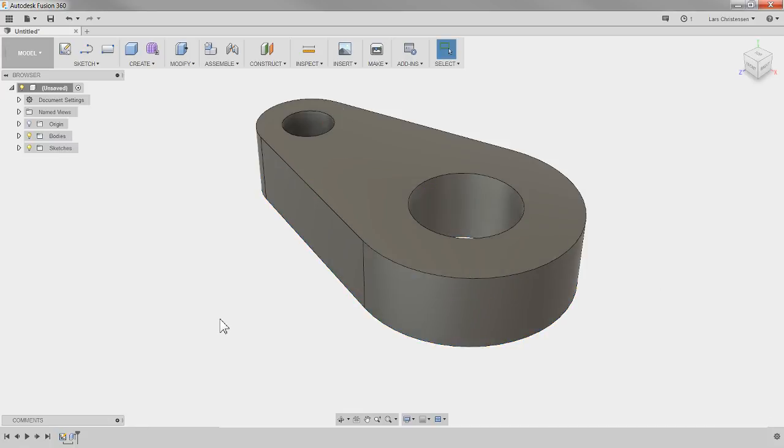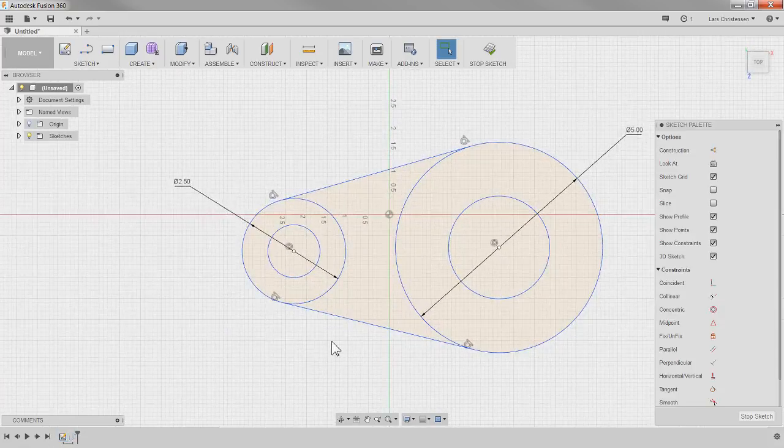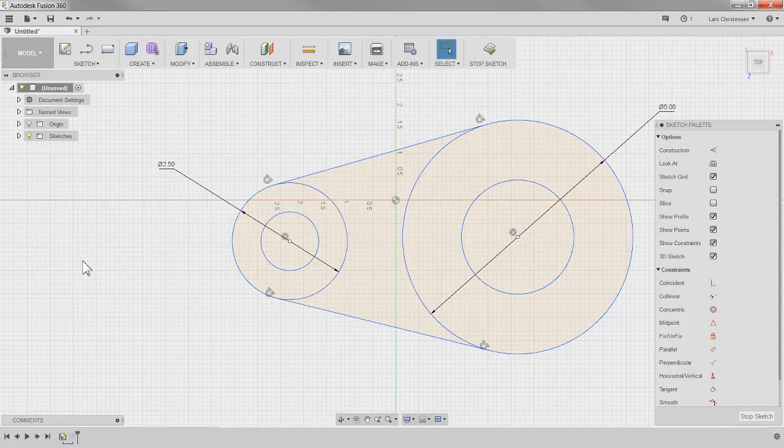Now another one you should definitely know about when we're talking about sketching is construction geometry. So you can actually create a line, and if you select the line, so hit escape to get out of the line, if you select the line and you hit X, it will become a construction line. That actually also works right over here. It's the same icon sitting right over here for the X command. And of course, a lot of these commands are everywhere.